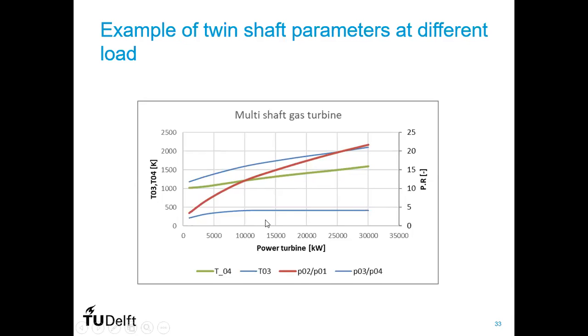The big advantage, if you look at part load performance, of a multi-shaft turbine is that you have quite a variation in the mass flow. With a single shaft, you run at one rotational speed, and especially when you are at the stone wall, like I just saw on the compressor curve, at the right side of those compressor diagrams, where you normally are with a high efficiency gas turbine, you more or less have a constant mass flow, unless you use IGVs. The big advantage of such a multi-shaft turbine is that you can vary the mass flow of air depending on the power you run.